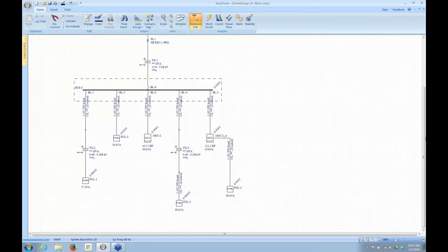What it really is, is a rule-based system for sizing conductors, sizing circuit breakers, and sizing transformers, based on National Electrical Code load calculation. And there are a few other checks that it does, like voltage drop.